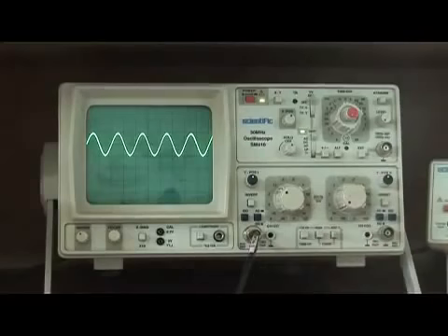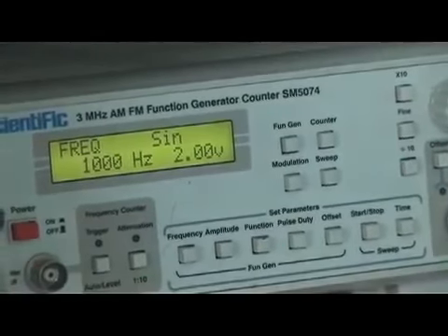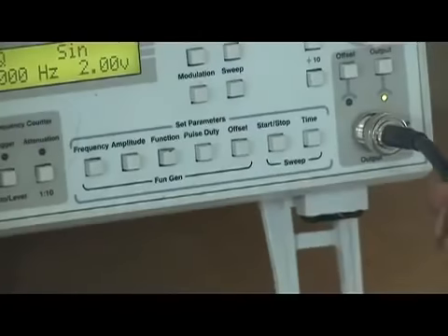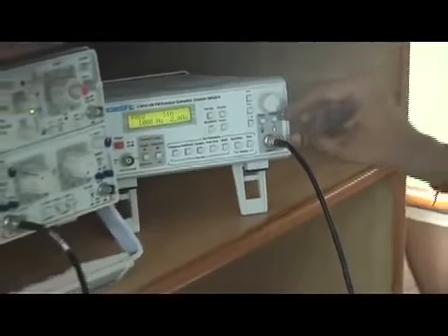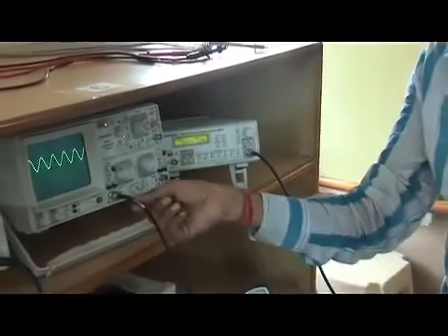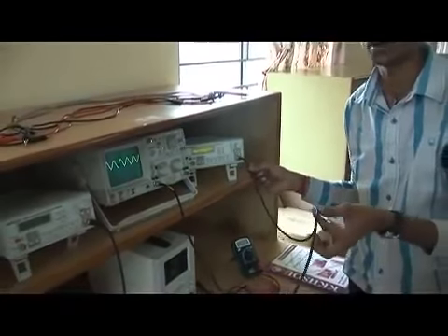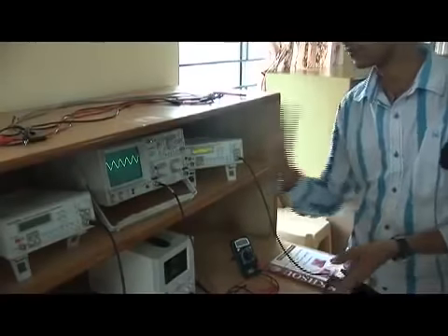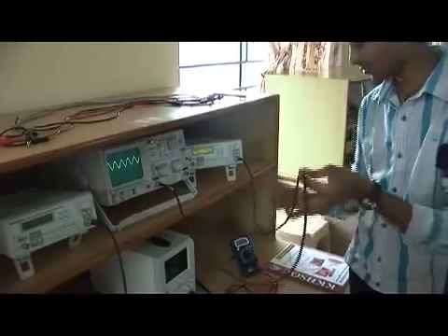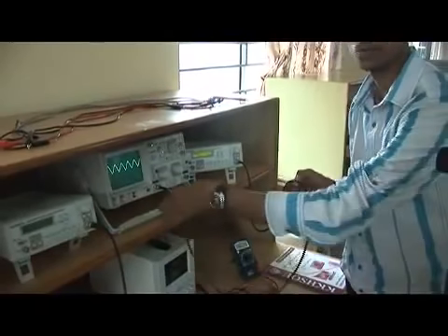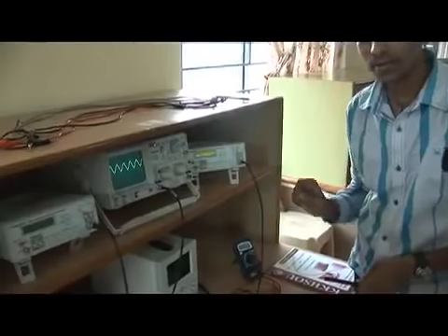So 1.9 volt. We were generating a signal of amplitude 2 volt. Now we are getting here a signal having an amplitude of 1.9 volts. So what happened to the 0.1 volt? When you transmit this signal from this wire to this CRO, this wire has some resistance. You know wherever there is resistance there will be a voltage drop. So due to the resistance of this wire, there is a voltage drop of 0.1 volt in this wire. That's why we are getting 1.9 volt. But we don't have to worry about that. It is a little error in electronics, this particular resistance of the wire. So this is how we calculate the amplitude.